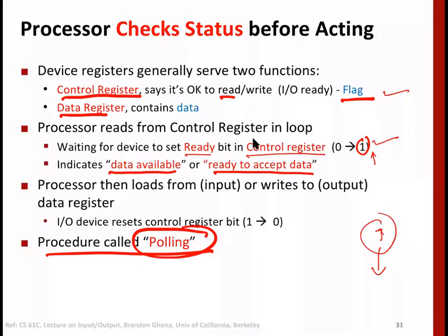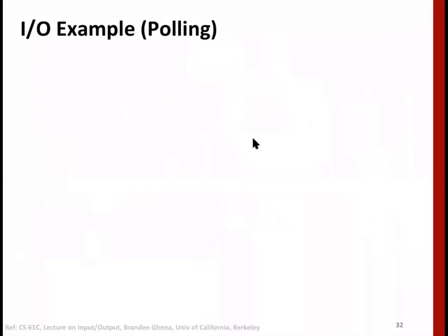So for example, right now, let's assume that the frequency of getting letters becomes just too high. Okay, you are expecting a number of letters every 10 minutes. Then you will say that maybe some other method is better for me, because you will get interrupts very often, right? So it totally depends on the scenario, but in general, this method of going and checking whether the bit is set or not may not be efficient for certain cases, right? And we'll look at some of these.